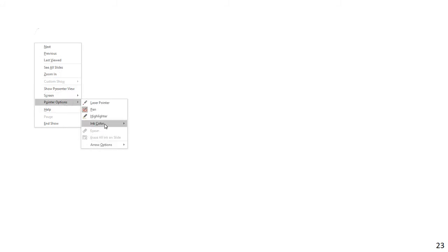Okay. So I have one other limit state that I want to talk about for tension members. Now, this isn't really a true limit state. This doesn't actually have anything to do with strength. This is more a constructability limit state, and we call this the slenderness check. The tension member slenderness check.